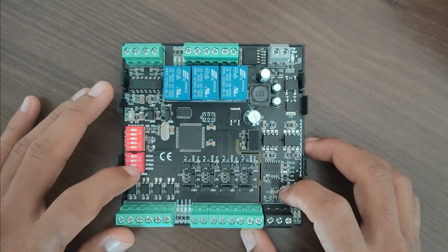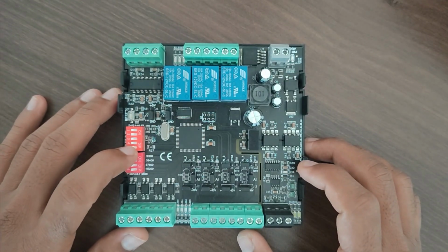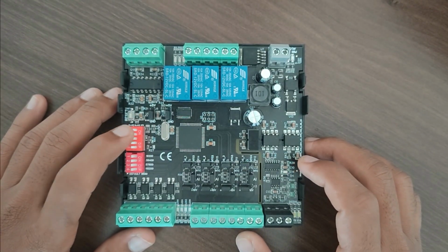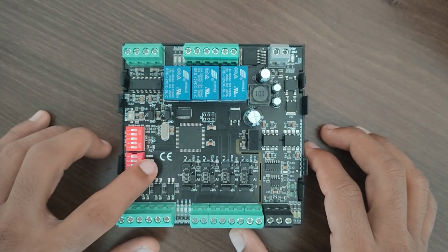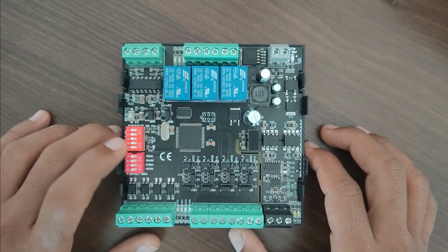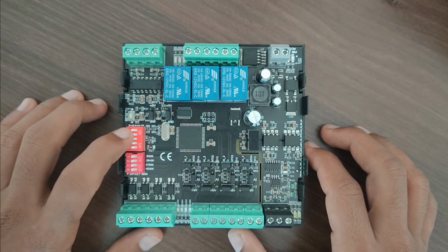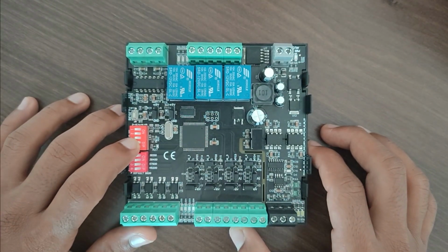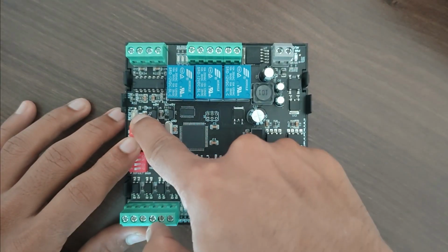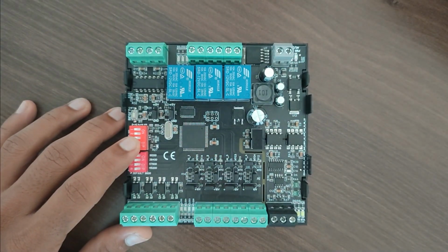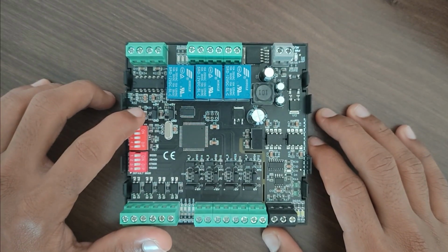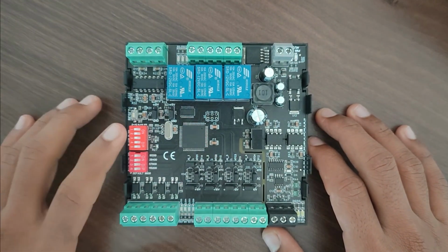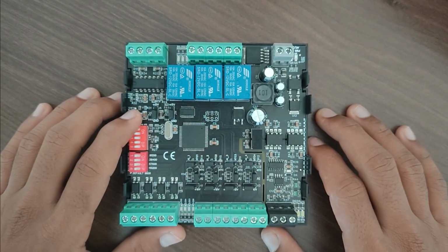And here we have the DIP switch part. In this DIP switch part, the user can set their own slave ID and the baud rates. For the baud rate part, here in the board they have mentioned already. And for the slave IDs, the user can set up to 31 slave IDs. And here we have the reset part. Whenever the user changes the slave ID and the baud rates, at that time just need to press the reset button. So the board will get configured with the new addresses.